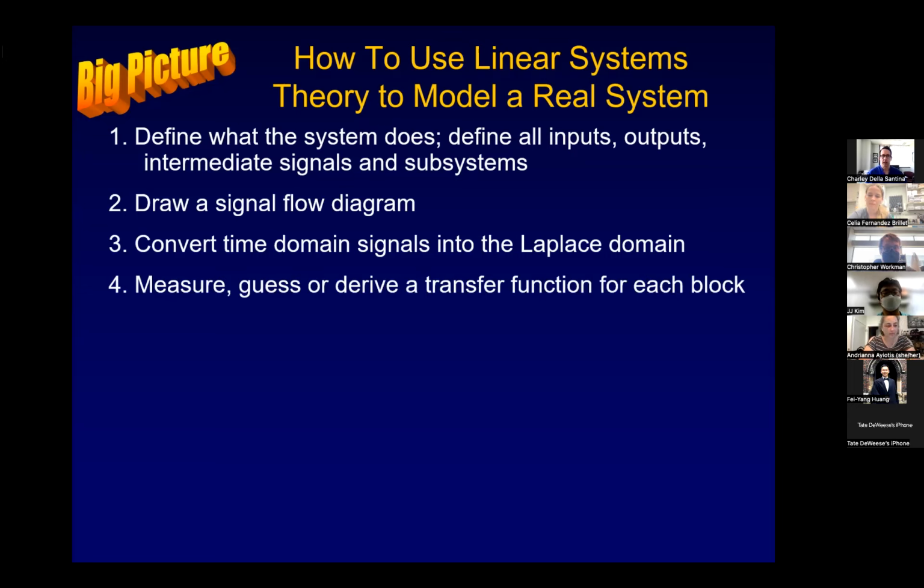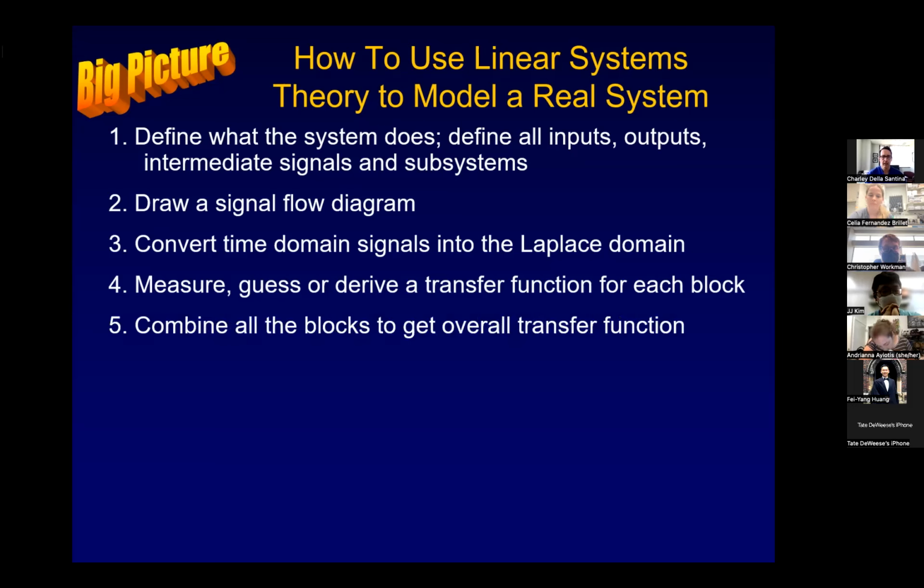Once you're in the Laplace domain of modeling time signals, then you either measure, or sometimes you just guess, or sometimes you can derive from first principles of basic physics a transfer function for each block, each subsystem, which tells you how it takes its input and turns it into its output. And then you can combine all those blocks together to get an overall transfer function.